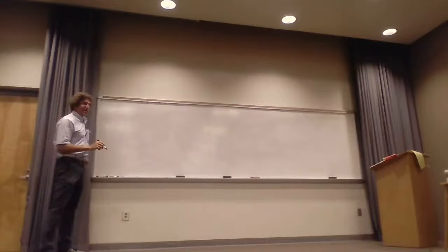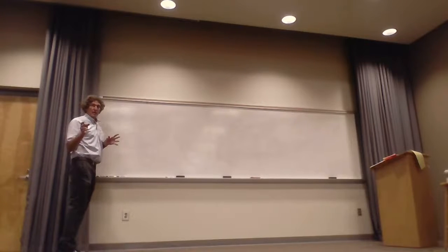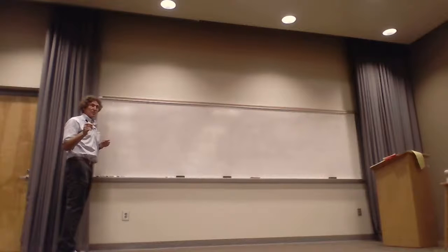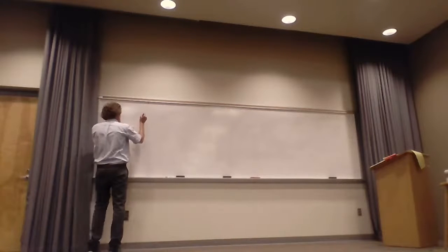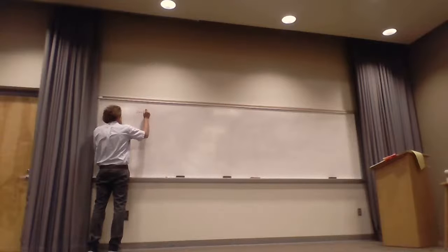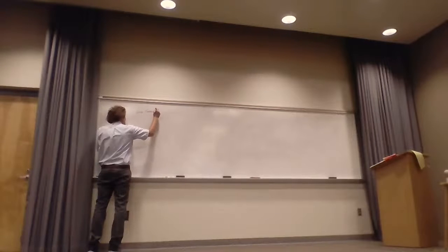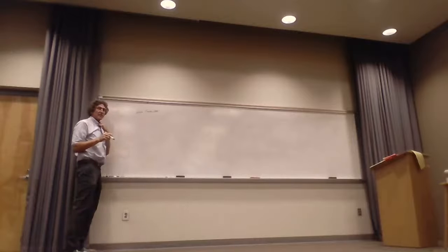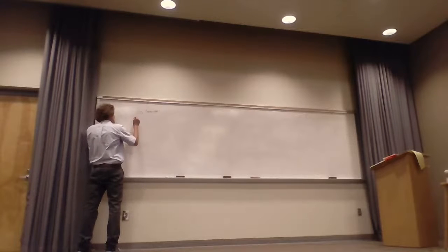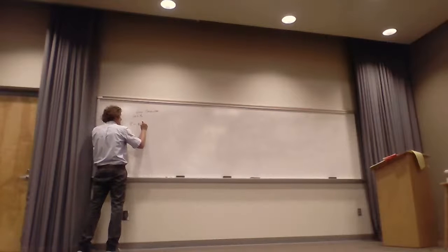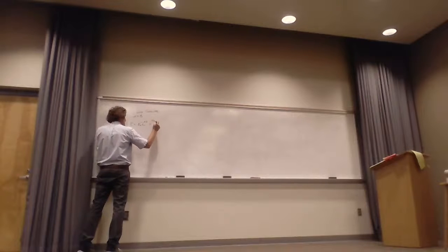So now we're talking about what the effects of a good conductor are on things like resistance. So this is going to be for good conductors. We have a good conductor, alpha is equal to beta. And in general, we know the E field is some E naught, e to the minus alpha z, e to the minus j beta z, in the AX direction.